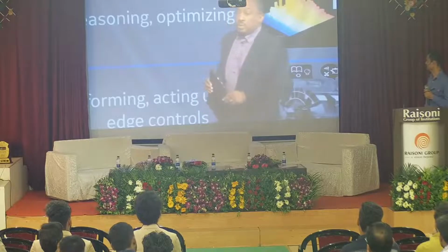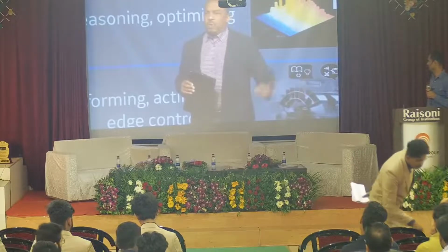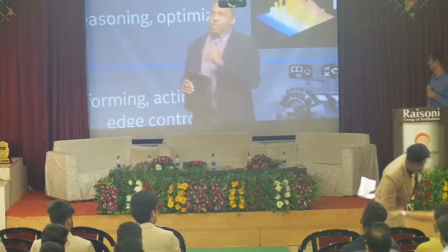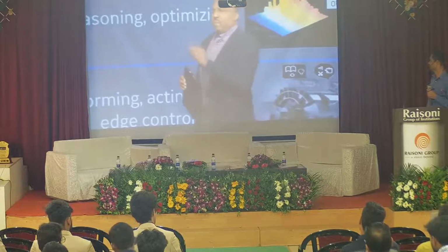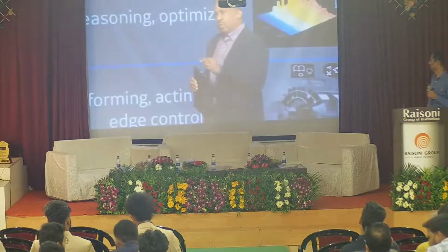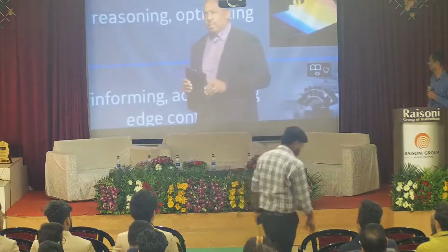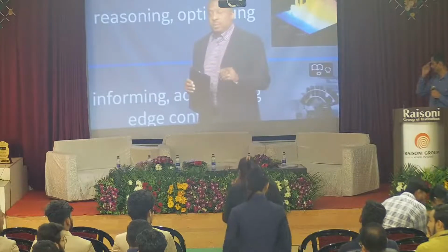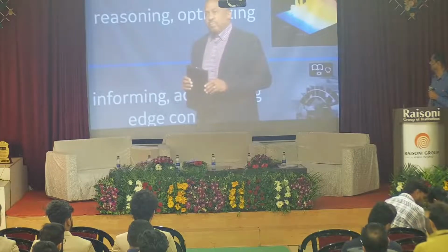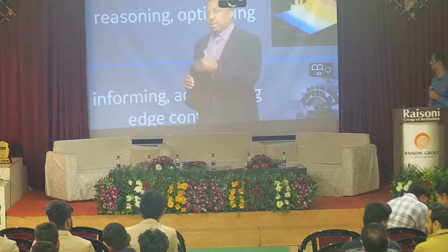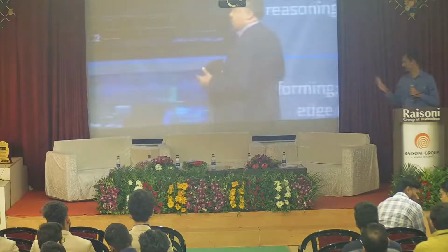Or you can use an app downloaded to the edge, running analytics on the edge, one of those boxes you saw previously. Now that app can run much more precisely. It can precisely monitor the load and the ramp rates, aligning them with the steam temperature so that the thermal stresses on the rotor are minimal. That's how you get to that 25% reduction number. It also, by doing that, allows you to start a lot faster and burn less fuel. That's where you see the other benefits show up. All of this executing on an edge device. That's see, think, and do. These are the digital twins working.